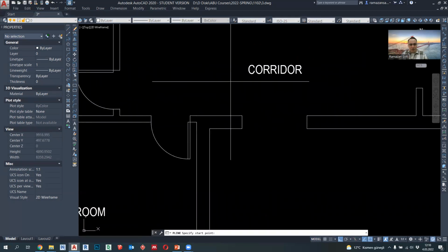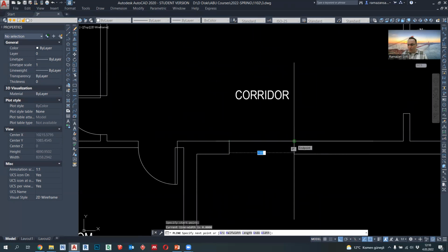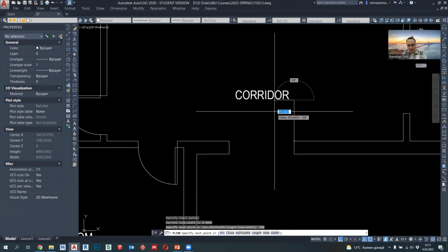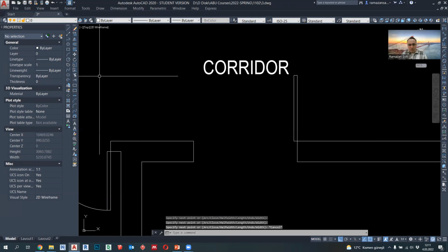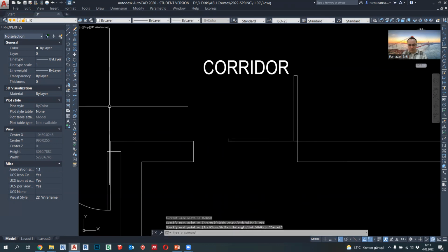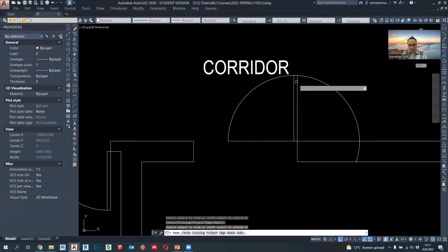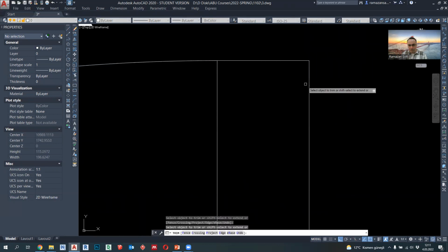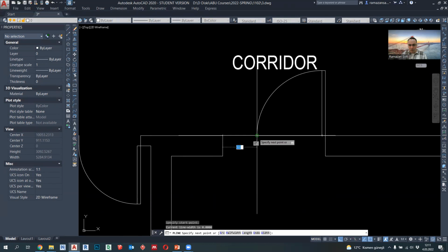Let's create a door opening at here also. So since the length is 1.5, we will create double door opening at here. One of them will be 1 meter length, which is set for 1 meter length. Let's continue. Yes. And the other one is set for 50 centimeters.